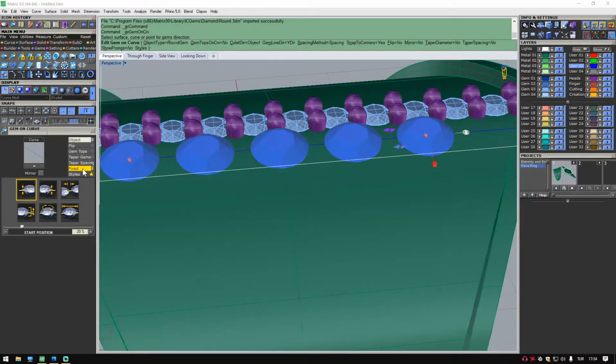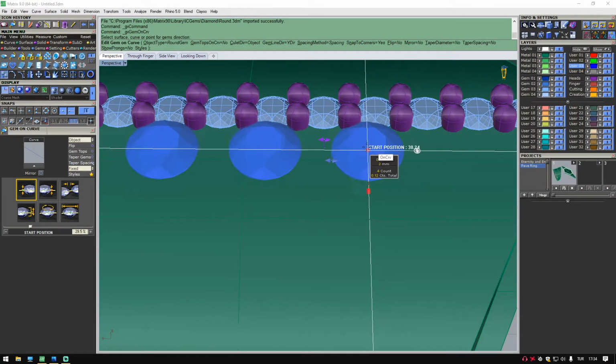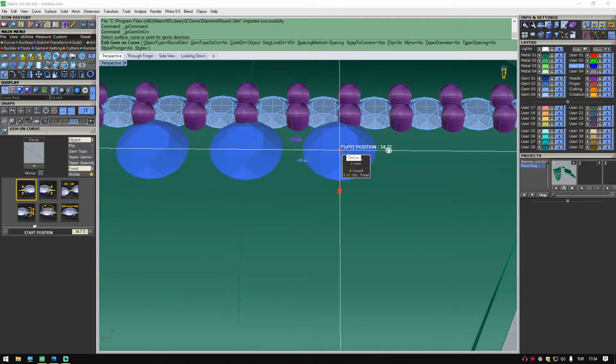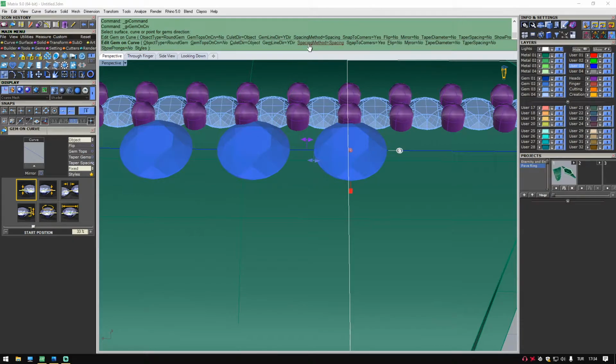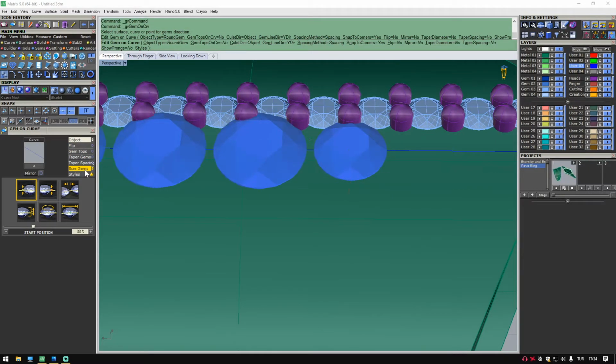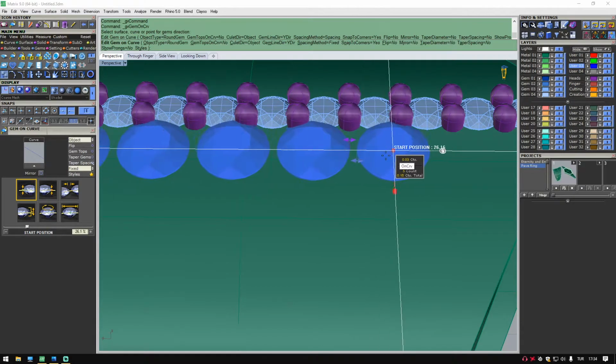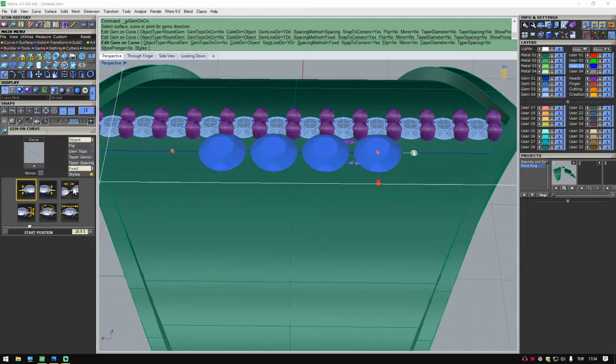Now here it says fixed, which is what I want actually, but when you move your stones, you can see that the spacing in between is not fixed. If you check up here, the spacing method, it says spacing, but I want it fixed. So if you see this one fixed, just redo it. Redo fixed again, and now the spacing is fixed. The spacing in between, we typed 0.13, and the sizes 1.3, enter.